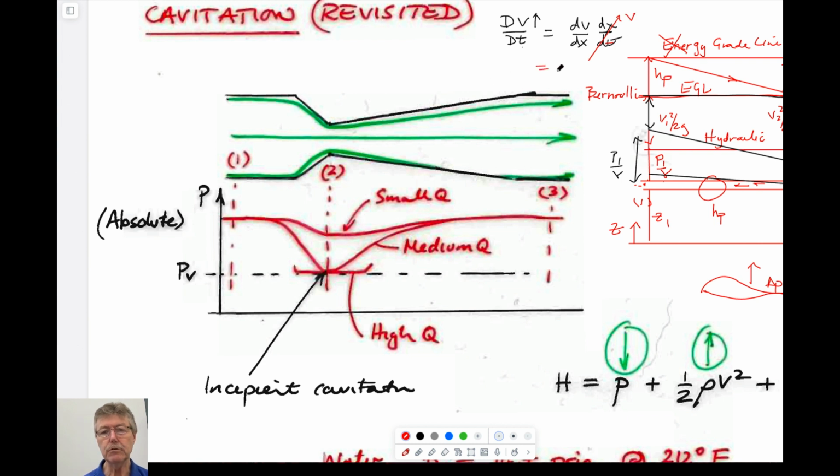So this term is equal to the rate of change of velocity in space multiplied by the velocity. This is the same as that acceleration. So this means that if you're at this point here, the velocity is changing as you move linearly along here. Clearly it is, because it's 1 meter a second here and 2 meters a second here. So this has to be finite, and this would be just the velocity here.